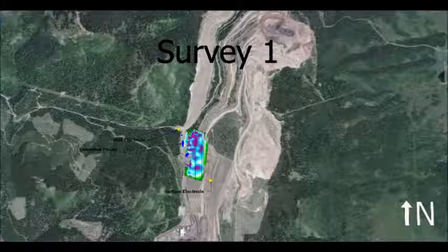The application of the Willowstick technology, as applied to the study area, is based on the principle that groundwater flow paths have an increased electrical conductivity than the surrounding earth materials. Therefore, the electric current highlights areas of highest saturation and transport porosity where meteoric water preferentially flows into the Wells Formation aquifer. Selenium concentrations rise above groundwater standards only during spring months.